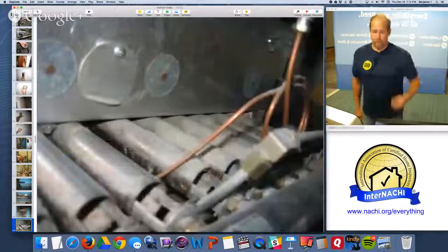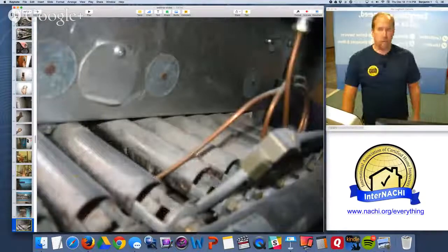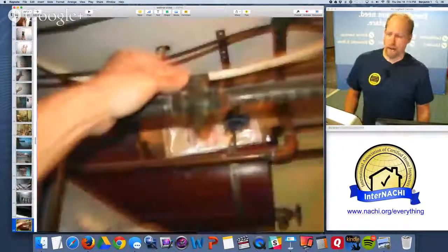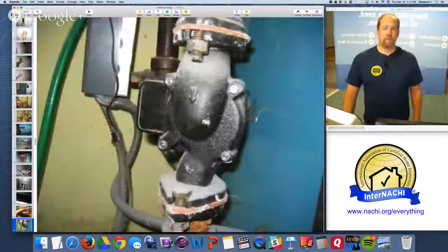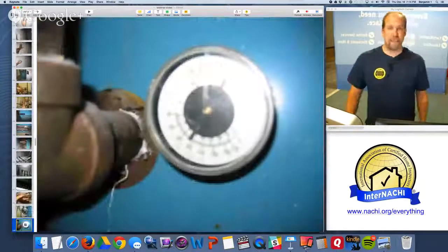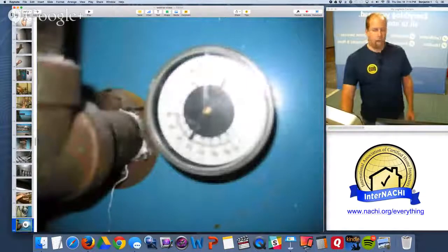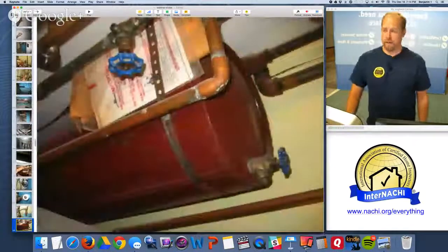These boilers get really dirty, especially oil-fired boilers. Gas boilers need to be cleaned, and this one hasn't been touched in many years. I like to look at the flame color if I can, or the service record. If it hasn't been serviced in the last year, I call it out. That's a pump. Pressure, water temperature gauges, TPR valve, safety devices.